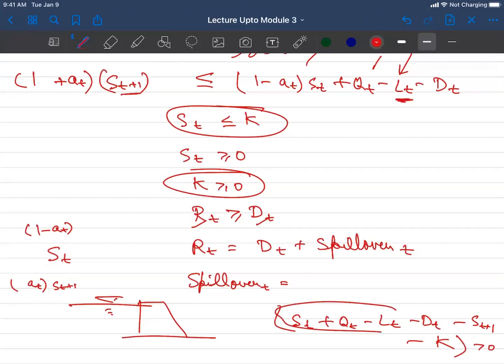This takes care of current time. This takes care of future time. Right? If at current time you have 10 units of water, you know that storage at next time unit is going to be 13. Your capacity of dam is 20 units. How much water you need to spill over? Your storage at time t is 10. Some water should be inflowing to meet this. Make sure that this is 30. You don't need any spillover. As simple as that.